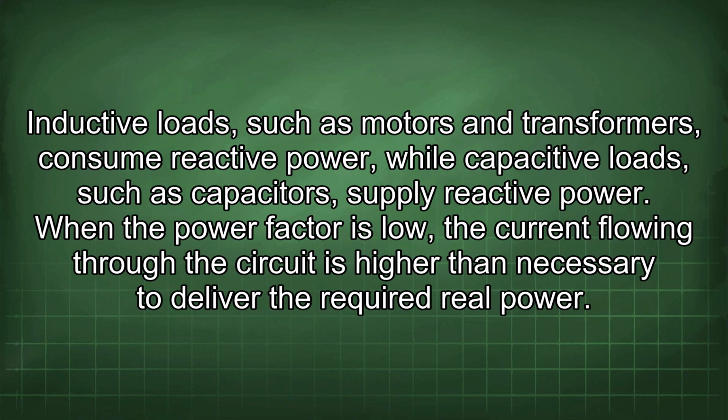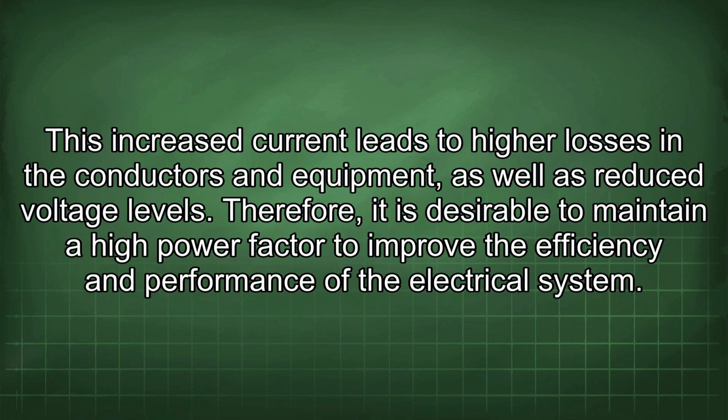When the power factor is low, the current flowing through the circuit is higher than necessary to deliver the required real power. This increased current leads to higher losses in the conductors and equipment, as well as reduced voltage levels. Therefore, it is desirable to maintain a high power factor to improve the efficiency and performance of the electrical system.